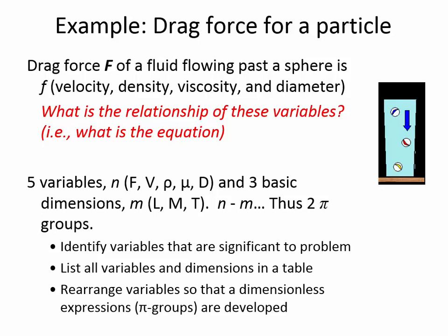If I have force divided by diameter, what are the units that are left over? It's going to be, right, m divided by t squared. So this unit grouping is simpler because now it doesn't have the length parameter in it. Okay, so how should I combine velocity and diameter to simplify the units of this velocity term? Same thing, just divide. So v divided by d will give me units of 1 over time.